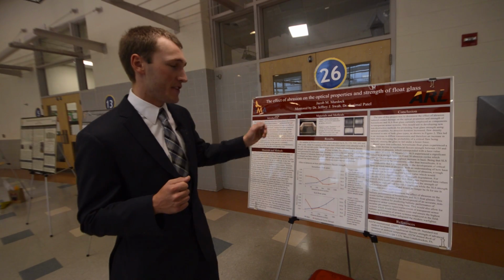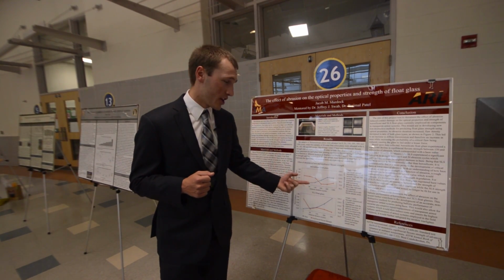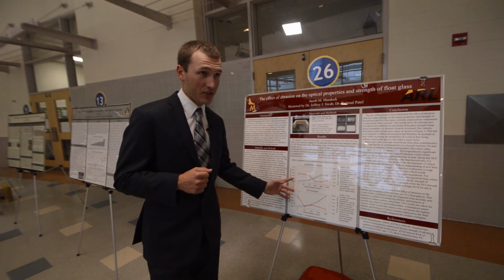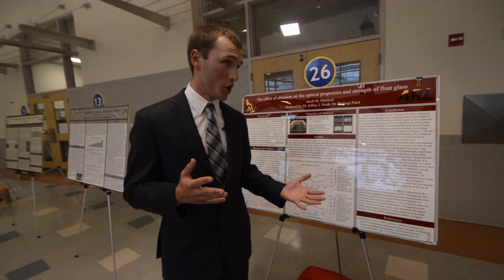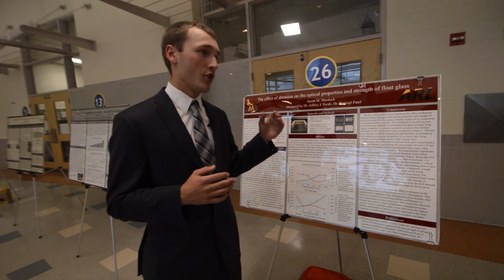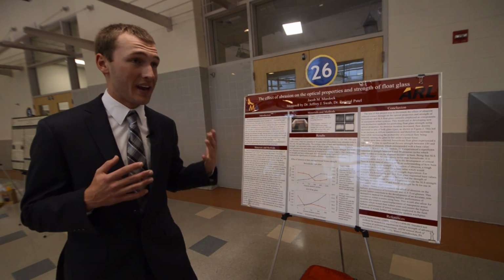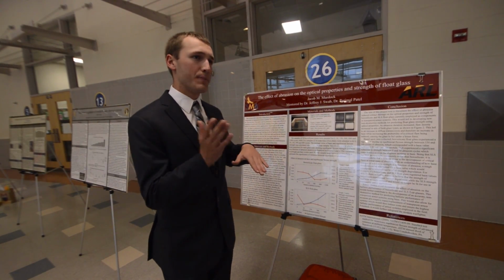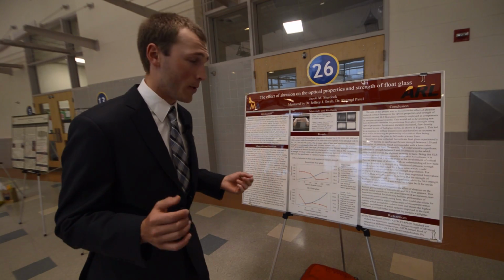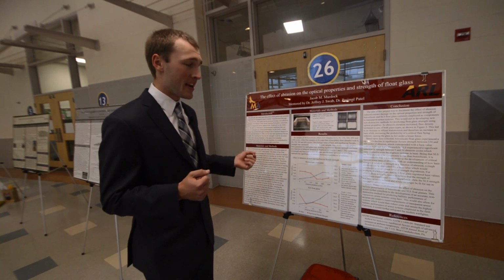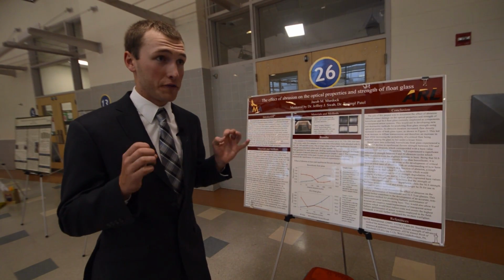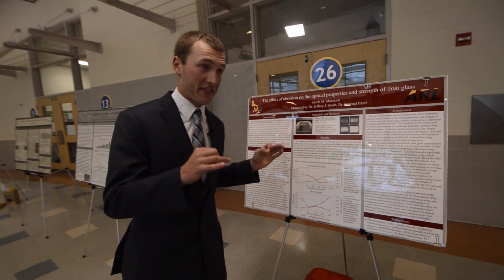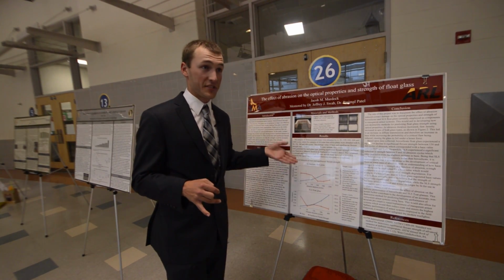As you can see from our results, as abrasion increased, in both glass types, the haze was increasing. As flaw density, the number of flaws on the surface, increased, you're going from a linear glass surface to a non-linear jagged surface, and light is being transmitted at a diffuse angle, causing haze to increase. At the same time, as flaw density increases, it's reaching a critical flaw density or critical flaw width and depth, causing the glass plate to fracture.